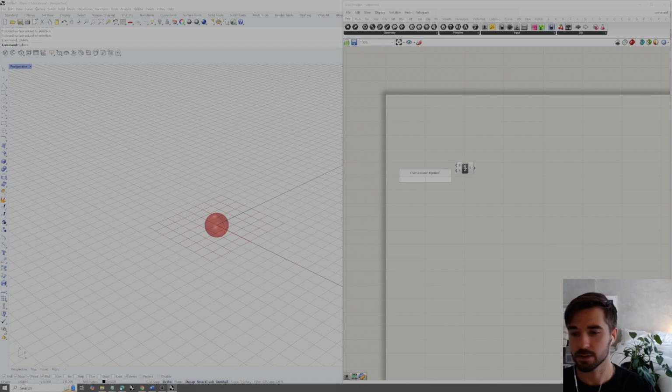So we can give this input constraint to the number slider by typing 1 and then a less than symbol, the current value that we would like this number slider to be at, which we can start with 4, and then is less than the maximum value of this domain, which we can say is 20. And then when we hit enter, we now have a number slider that starts with a current value of 4, which was that middle value, a minimum of 1, and a maximum of 20.